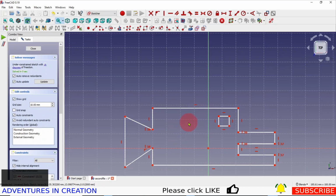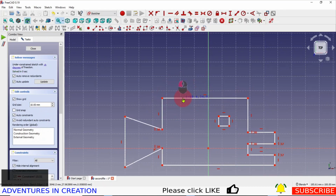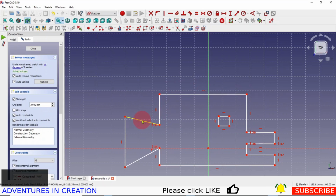multiple alignments that are in the right spot, and we can look for things like symmetry or angular alignments, tangential alignments. We can check if our sketch is constrained, if it's sitting together, by moving it like this. If these points were not attached, it would move separately. So you can see all my points are actually attached to each other, so nothing is coming loose, which is a good thing. That's the advantage of using a polyline.